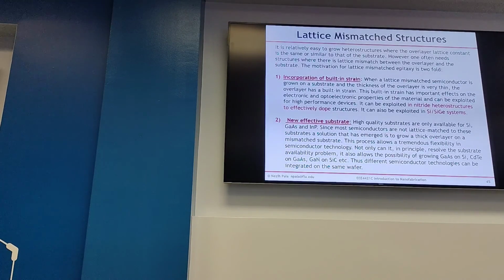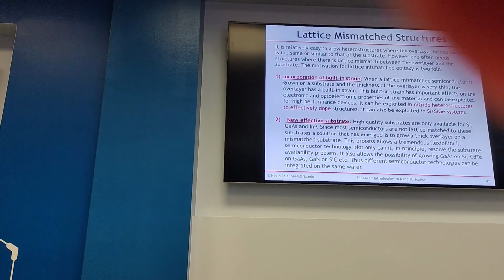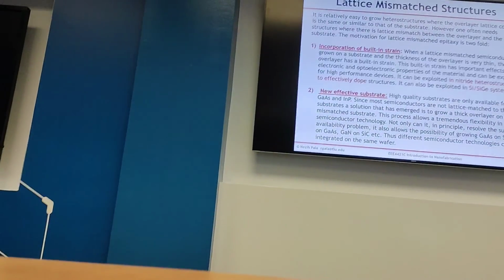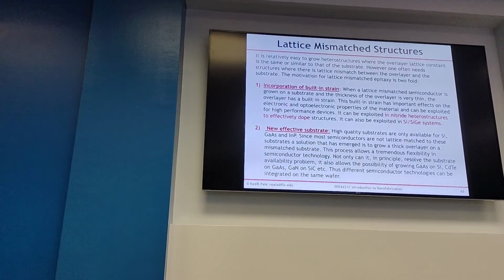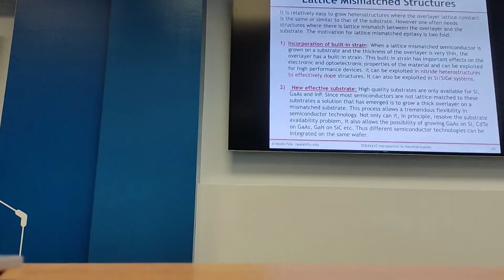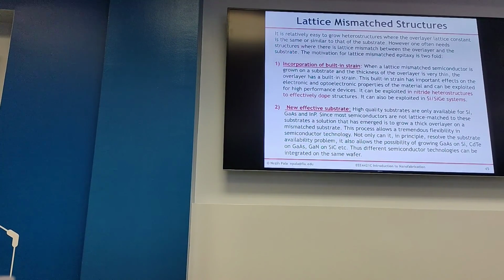That's one benefit. Same for gallium nitride or nitride-based devices. When you strain them, there's an induced electric polarization or electric field in the material which pushes the electrons to a channel, so you will get high carrier density in the 2D electron gas channel. So that's why you have very good transistors for gallium nitride. You don't have to introduce dopants to increase the electron concentration.